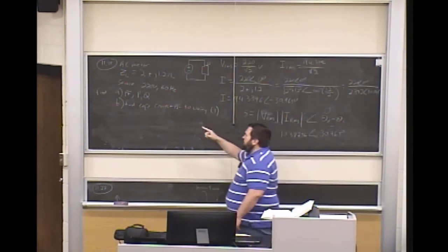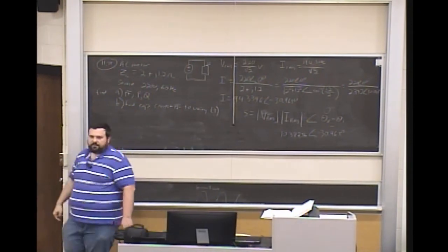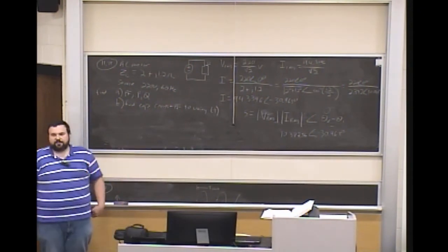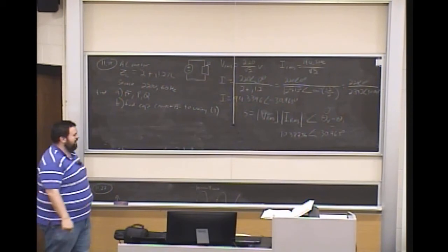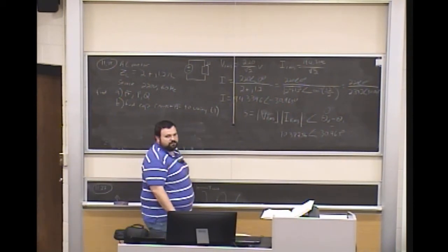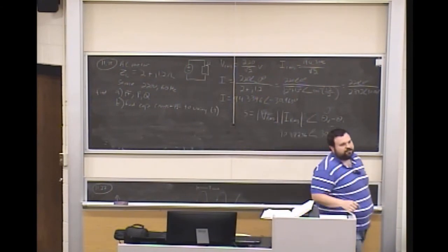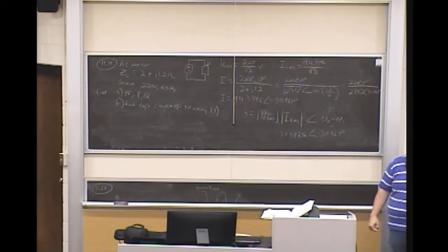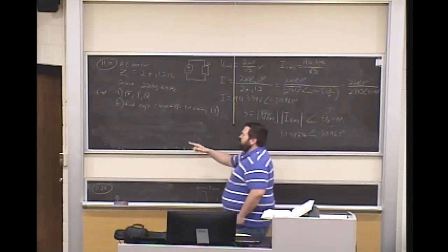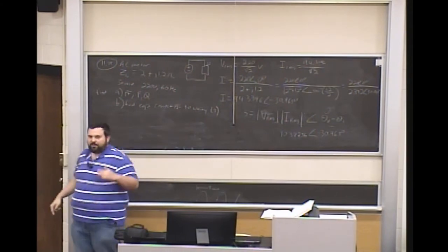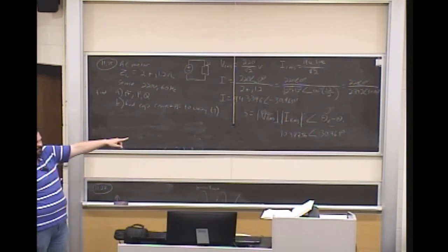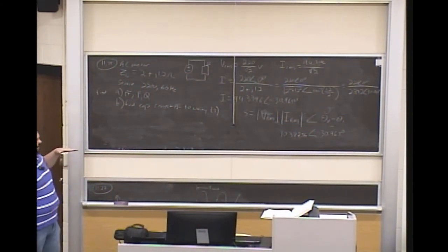All right, so now let's start answering the actual questions. The P turns out to be the real part of this, and the Q turns out to be the imaginary part of this. The P is the real power, and the Q is the quadrature power. That's the imaginary. Okay? And what we ultimately want, the power factor, is going to help us understand the ratio with our total power. So this S is our total power, and that's made up of a real and an imaginary component.